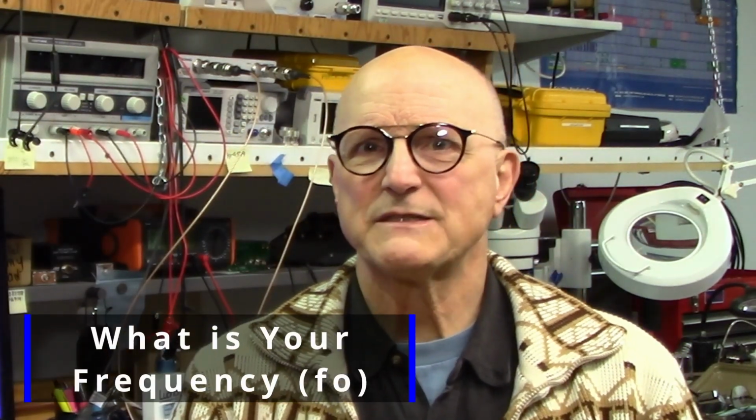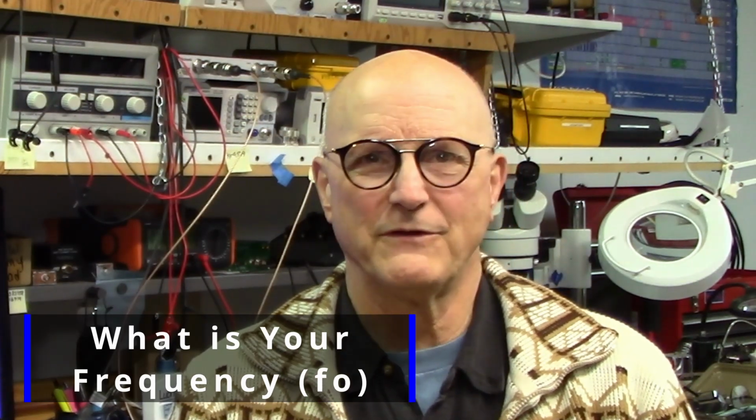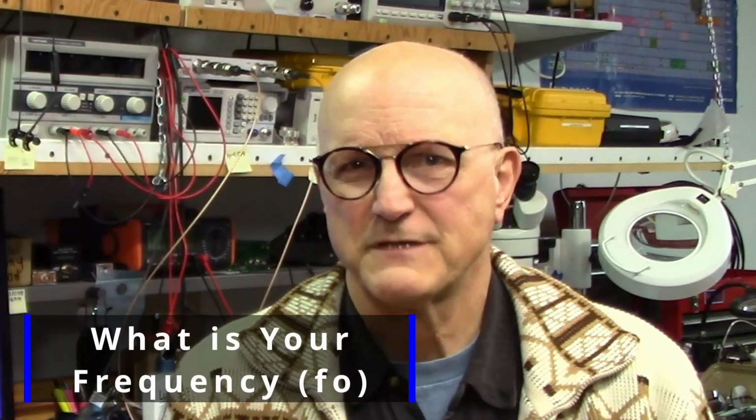It is best if this velocity factor includes everything associated with your stubs. Your connectors, your adapters, your T's, everything. Well, the next step is to determine the specific frequency you want to notch out using this band reject filter. I'll call this F sub 0.